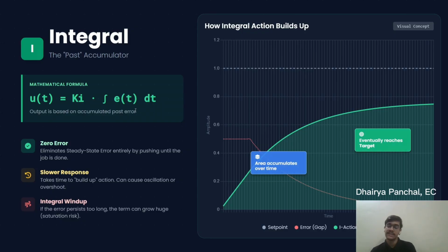So what this means is that at t tends to infinity, at infinite time, your system would reach your set point value. This means that your system response is very slow because it takes infinite time to reach your set point value. But here there is no error margin. What I mean by that is, here your system is never going to overshoot.